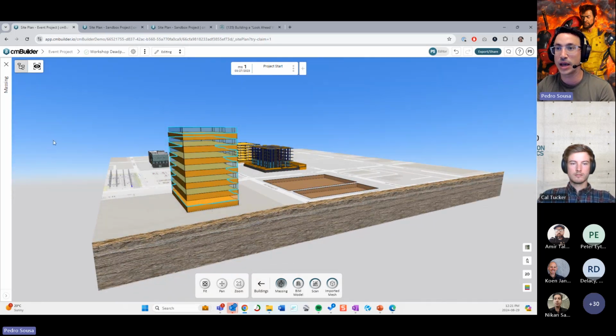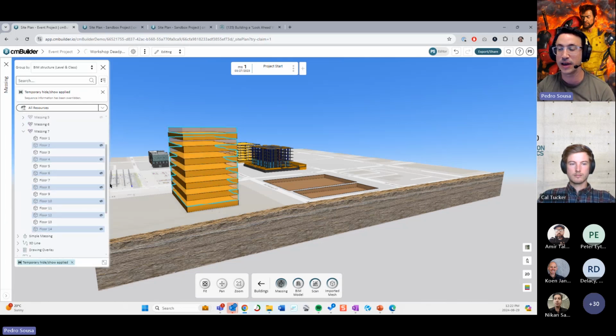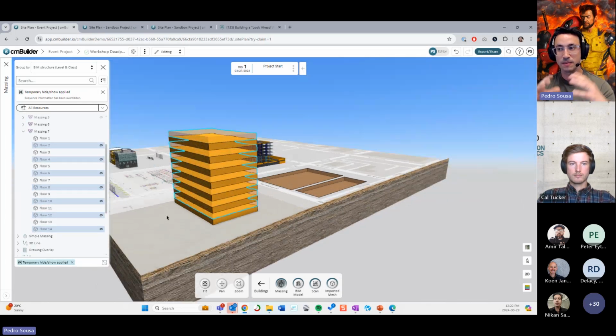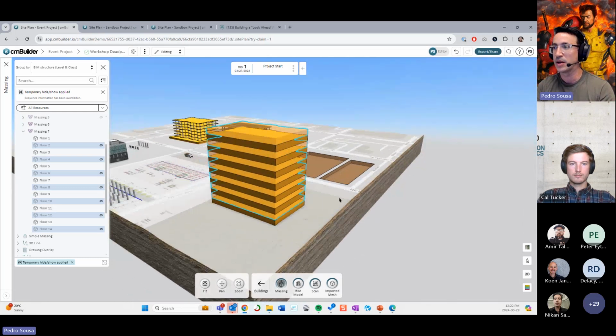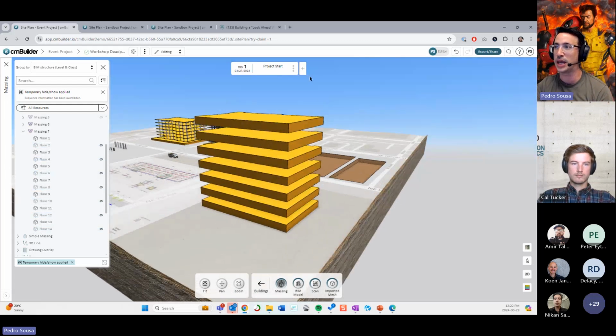The reason why I'm hiding these objects on the first milestone is because the detail massing is using a legacy sequencing method where you hide and show objects per milestone, but this is changing on the next version that's coming in 3 weeks, right? But basically what I'm doing is hiding these intermediate levels on the first milestone because I don't want to see them anymore in any of the other milestones.